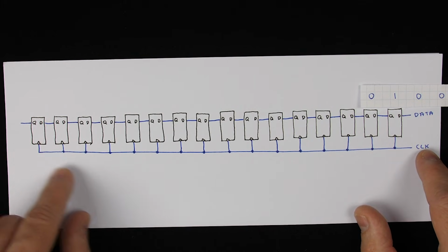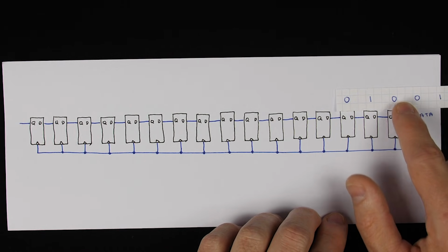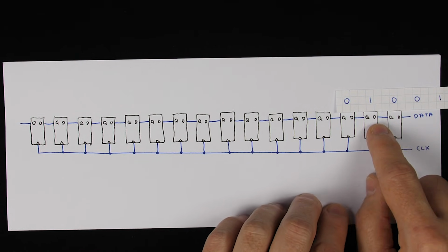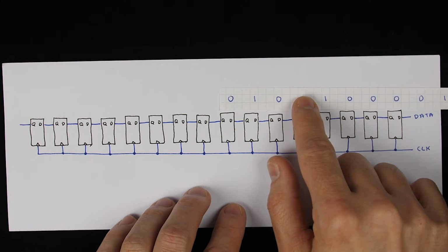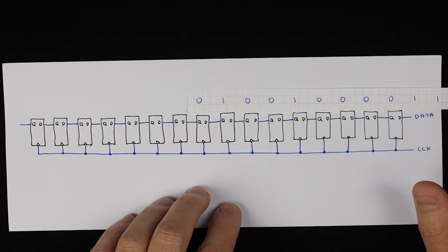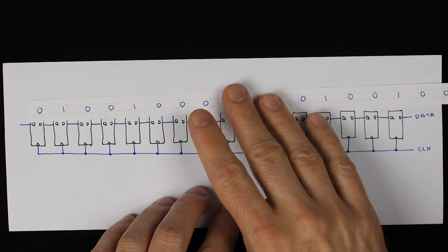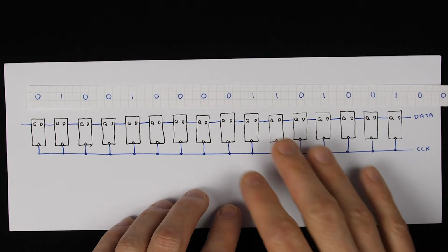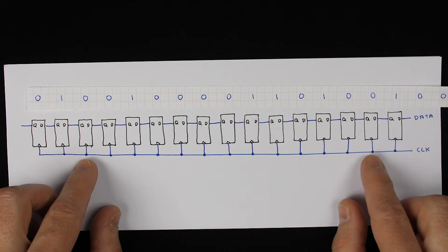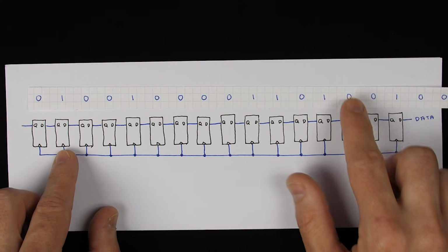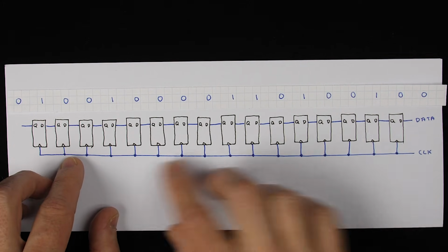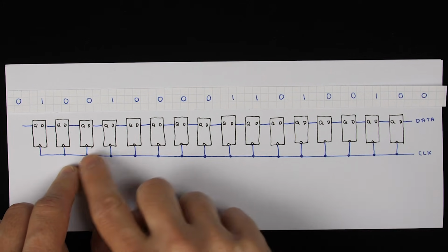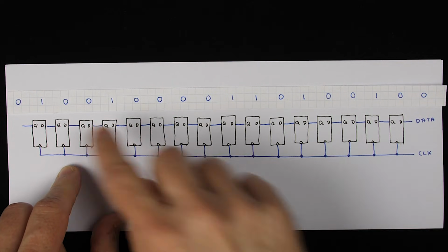And so with each pulse of the clock, each new data bit will get read into the first D flip-flop here, but then each subsequent data bit just shifts along down this shift register. And so this gives us something very much like that sliding that we're seeing as part of our CRC algorithm. So it seems like this would be a good place to start, with a 16-bit shift register like this that we can read all of our data into. And then once we get this working, we can start to think about, okay, how would we flip certain of these bits under certain conditions?